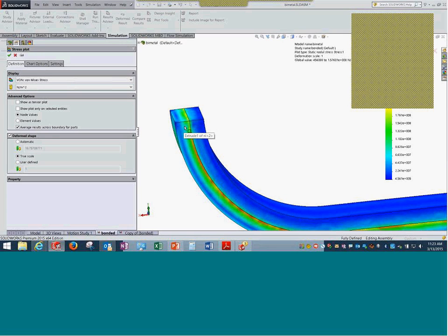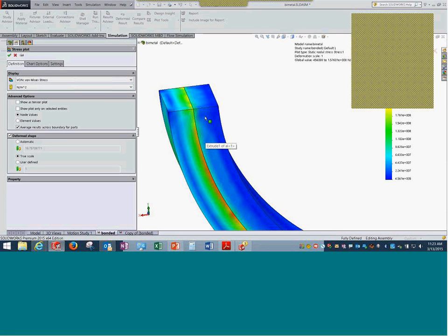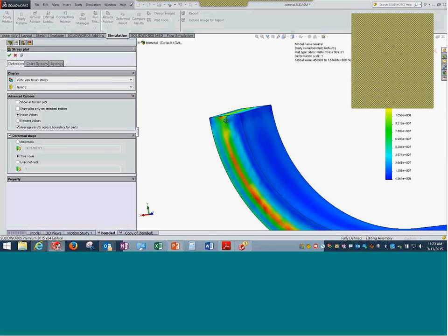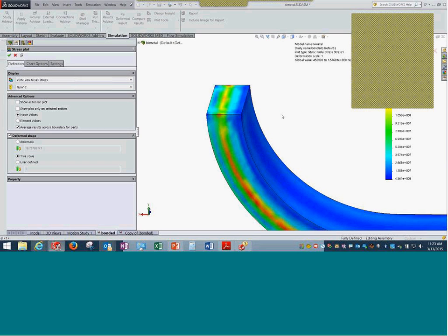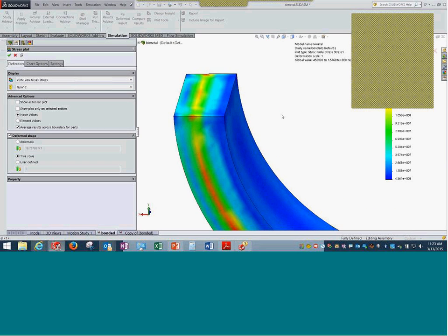Obviously, the stresses would be different in these two parts based on their own material. So this option gives us the capacity to average it. You can see a difference between nodal and elemental results across two parts of different materials. So I'm selecting the nodal values.